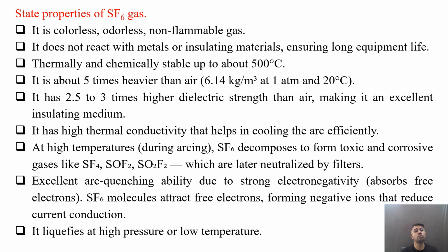It has 2.5 to 3 times higher dielectric strength than air, making it an excellent insulating medium. It has high thermal conductivity that helps in cooling the arc efficiently. At high temperatures during arcing, SF6 decomposes to form toxic and corrosive gases like SF4, SOF2, SO2F2, which are later neutralized by the filters.